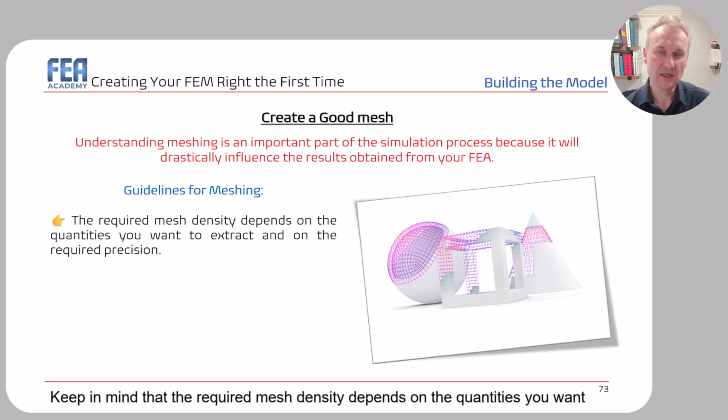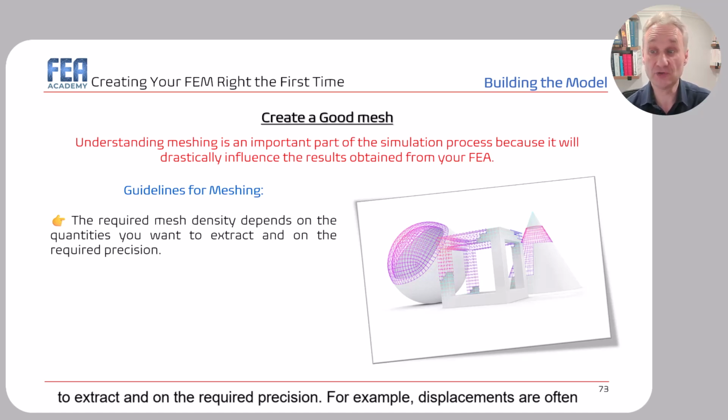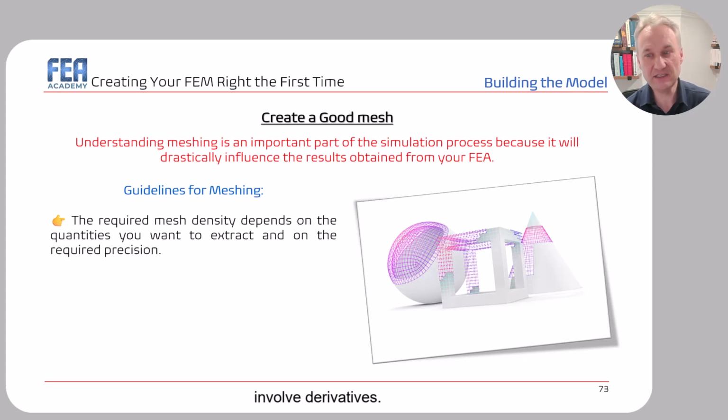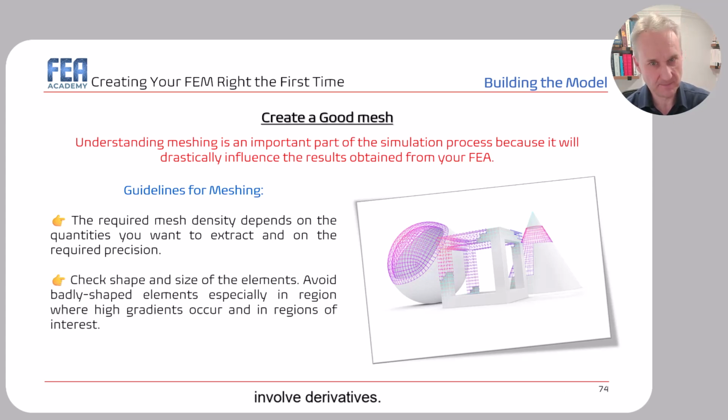Keep in mind that the required mesh density depends on the quantities you want to extract and on the required precision. For example, displacements are often calculated more precisely than stresses or strains because stress and strain involve derivatives.